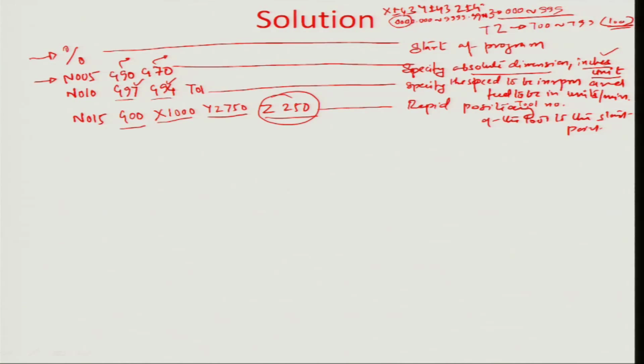In that format, the decimal is represented to the 3rd place, and then there are 4 zeros which are immaterial even if you don't write them. That's why you describe z as 250 and positive, because it is moving away from the work. So you have the tool going up from the surface by 1/4 of an inch, and that's where the docking position of the tool is, as represented in the question.